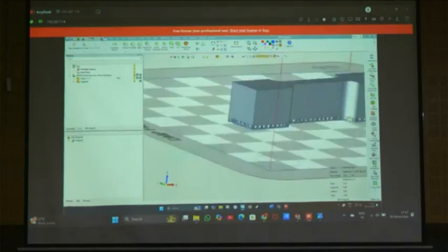Again, if you change the position also, you need to do the slicing again. We didn't change the position, but we have changed the support type, right? So again we need to calculate slices. The same story will happen. We calculate slices and scanning parameters, again the slicing viewer, these things will happen. But usually we cannot go for one sample print. We can fill the build actually. Since we have less memory on the laptop, I use it like this. But there we can see actually.